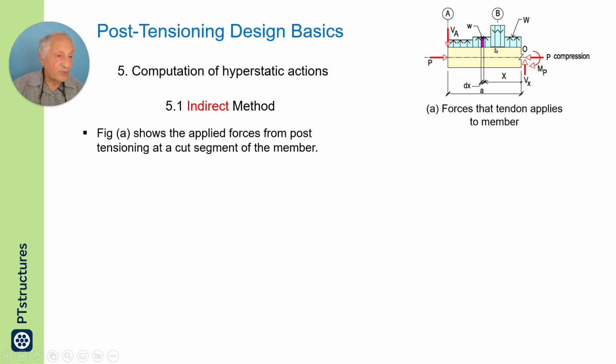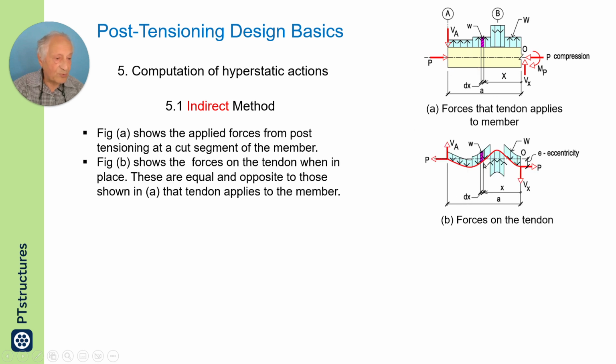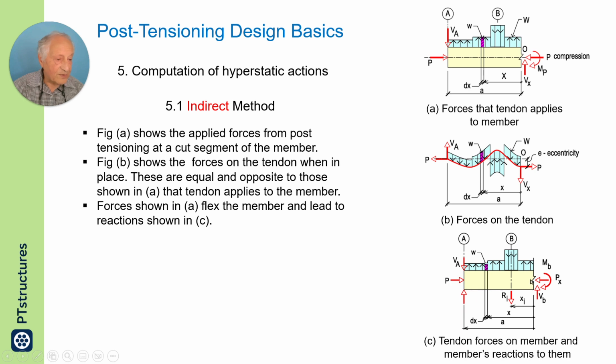If you look at the top right, I am showing you the forces from the tendon at a cut. I am not showing you the reactions here, but because it is supported, it is shown here. If I support this member as it is in real life, there would be a reaction here and there would be a reaction here. Otherwise, the applied force is in equilibrium here. The tendon force is in equilibrium here.